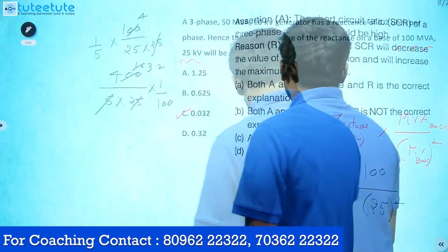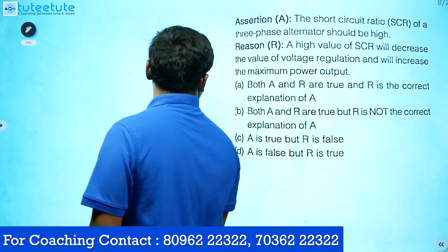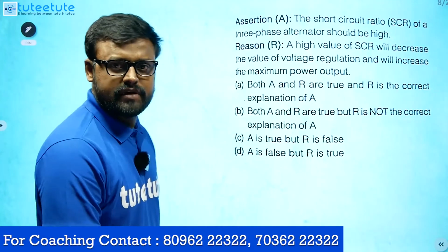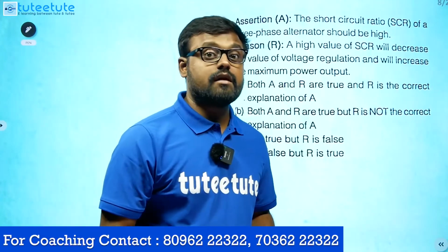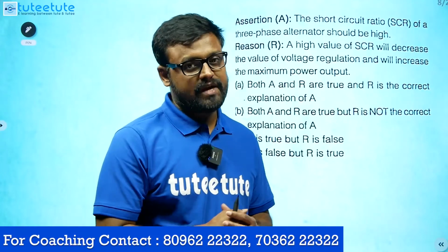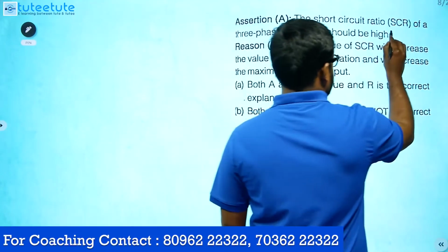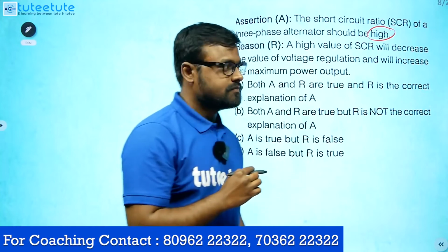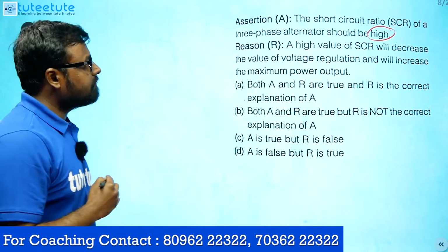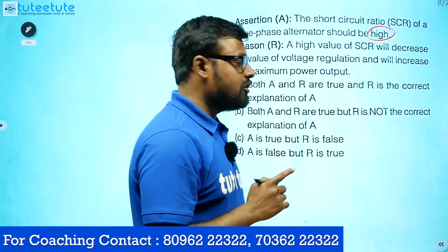The short circuit ratio of a 3-phase alternator should be high. Yes, it should be high because there are many advantages. That's why it has to be high. A is correct. A high value of short circuit ratio will decrease the value of voltage regulation.